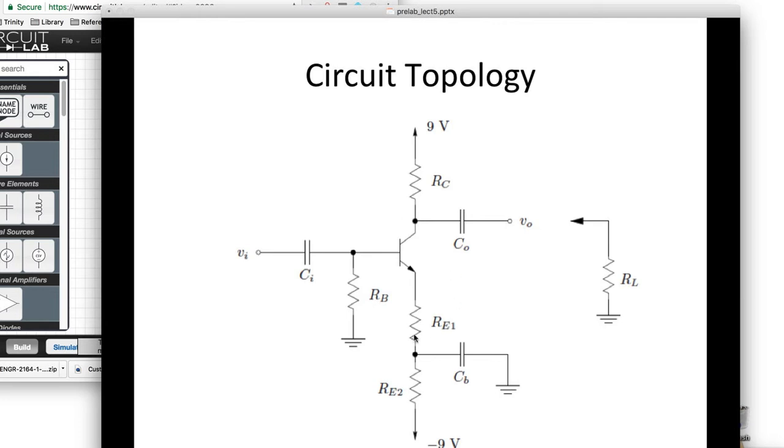from DC that's going on inside the amplifier and from DC at the output. So these are chosen to be essentially a short circuit at the frequency of interest and an open circuit at DC. So they're coupling capacitors, just like when you use an AC coupling capacitor on your scope. It does the same thing. Since this is lowercase, we assume that VI has no DC associated with it. And if it did have any, we wouldn't care, because we're going to get rid of it using CI. So CI and CO are coupling capacitors, and they're used to just disengage the DC that's present at VC here, for example, from the DC at the output.